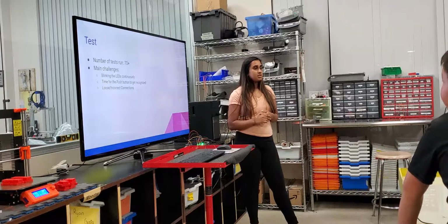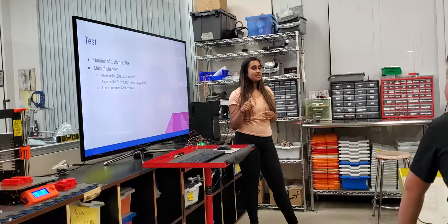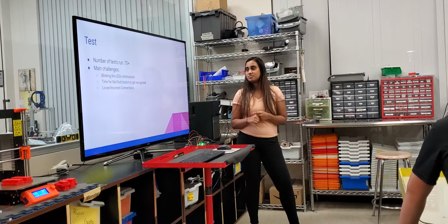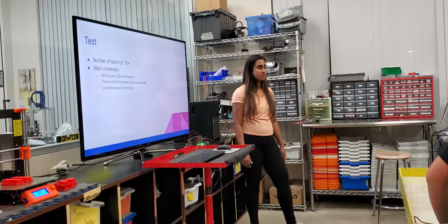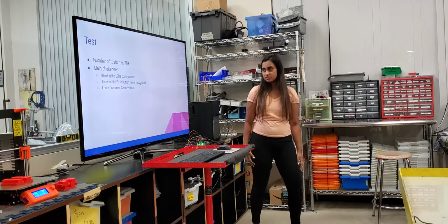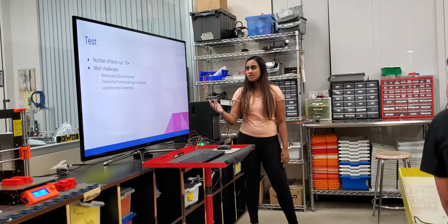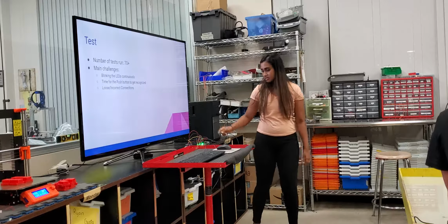So sometimes if an LED is blinking, if we're in a loop, and you press the push button, it doesn't get recognized immediately, so that's kind of like a delay, you could say. And incorrect connections or loose connections on the breadboard.